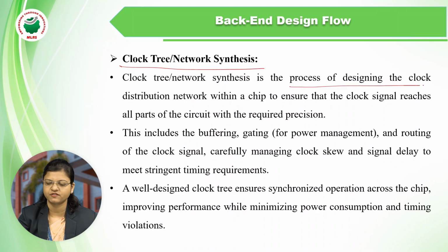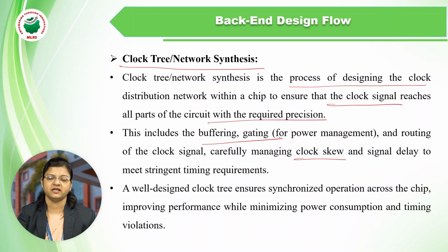It is the process of designing the clock distribution network within the chip to ensure that the clock signal reaches all parts of the circuit and each block, whether it is a sub block or main block, with the required precision. If we are not doing proper clock synthesis, then we may face the issue of clock skew, and in this context we have to see the clock gating also.